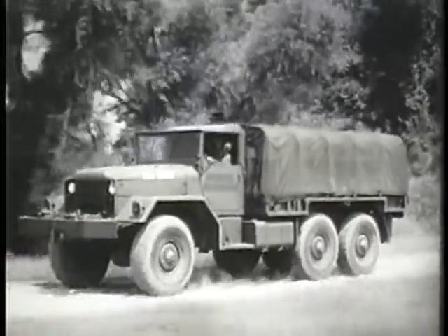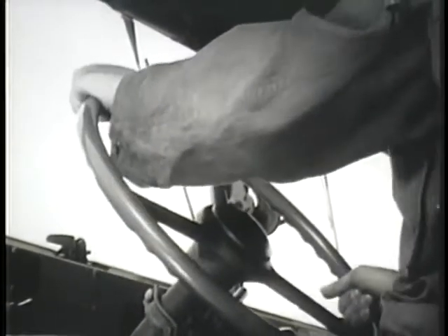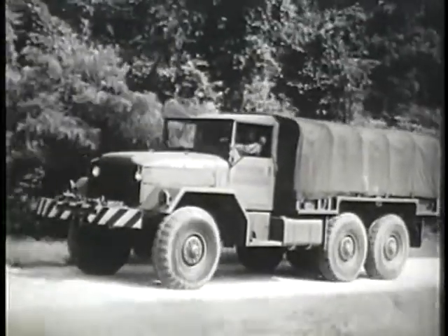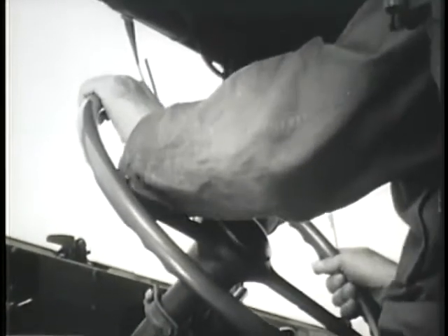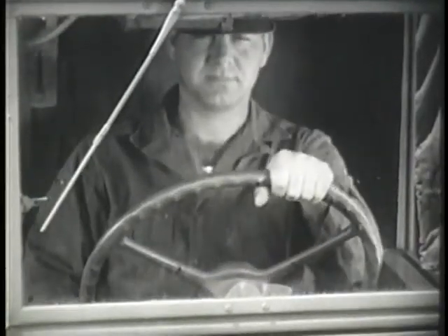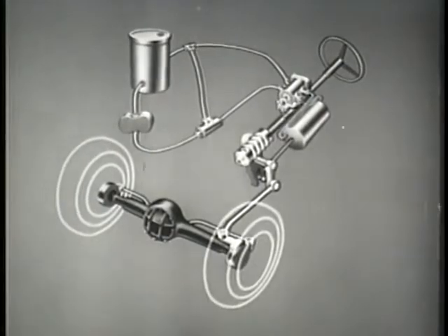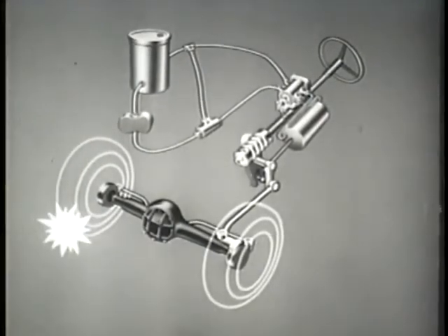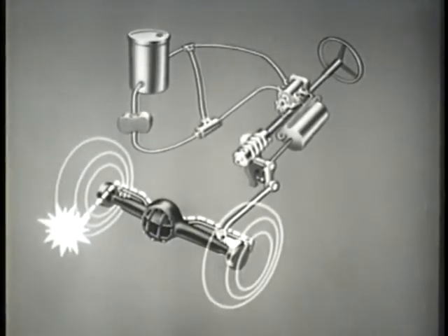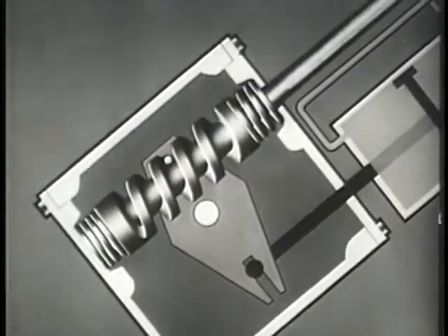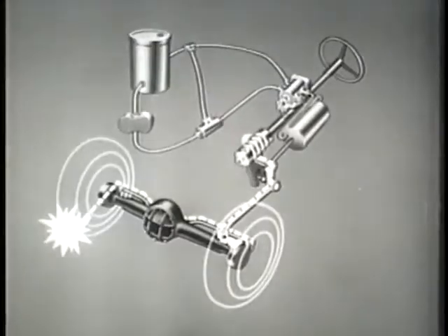One of the steering problems of the heavy vehicle with cam and lever steering is road shock. Road shock causes kickback of the steering wheel and makes control of the vehicle difficult. On the other hand, heavy military vehicles equipped with hydraulic steering resist road shock through a reverse action in the power cylinder. When one of the front wheels is subjected to road shock, the shock is transmitted through the steering linkage to the pitman arm and the pitman arm shaft lever. The pitman arm lever then actuates the cam, causing it to move up or down depending on which wheel receives the shock.